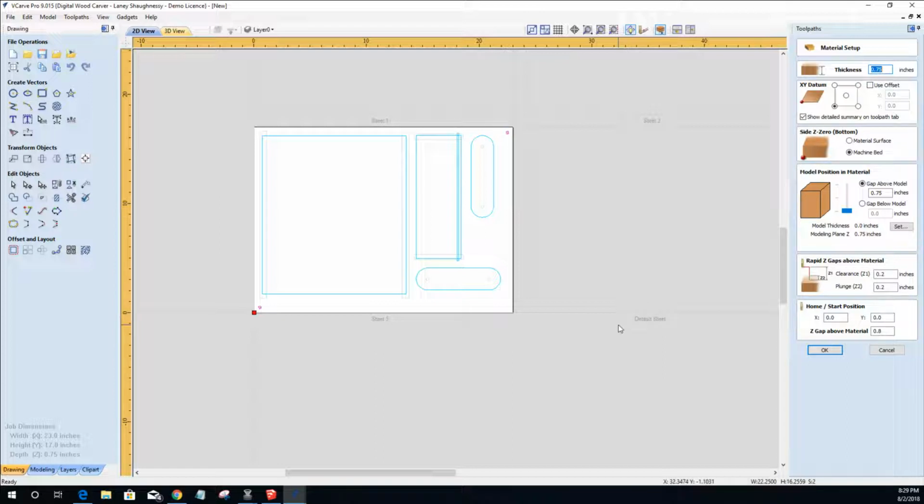Well, when I'm actually drilling the holes in the waste board, when I touch off my Z, instead of that being 0 on the wasteboard, I'm just going to touch off to the wasteboard, and I'm going to set that Z as 0.75. I'm going to say that this point is 0.75 from 0 for this particular cut. So that way it cuts the holes in the top of my wasteboard 1/4 of an inch deep, instead of carving air.